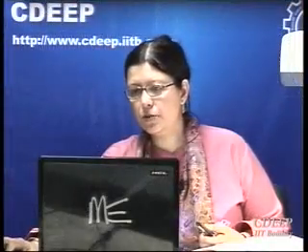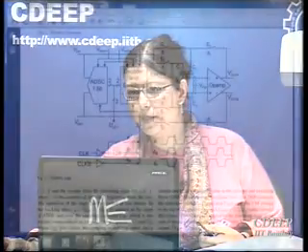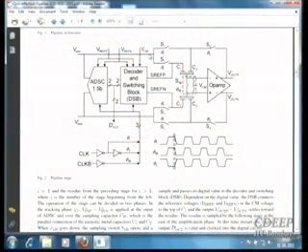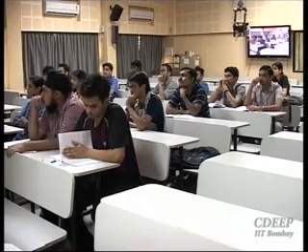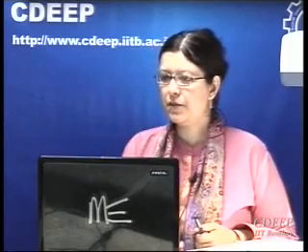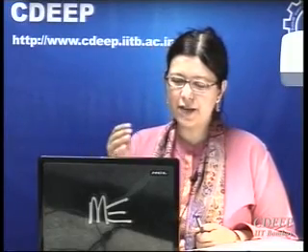Because when you are in the tracking mode, this will get disconnected and then input will be connected to the signal, which is coming either directly from input or from the previous stage. Yeah, there is a switch inside. That's why it says decoder and switching block. Because we had only binary, multiply by 2. We had only a gain amplifier. We didn't have shifting. Here we are adding and also we have adder as well as multiplier, right?